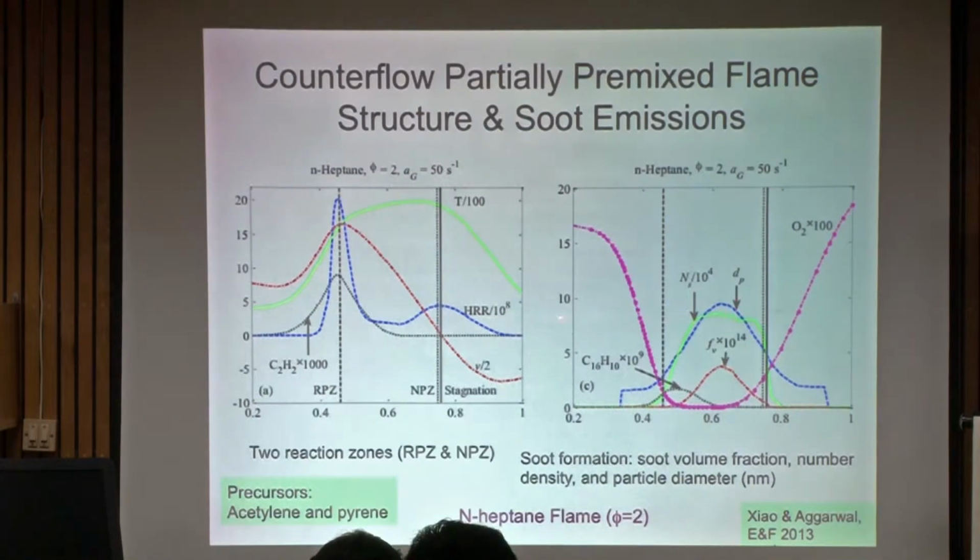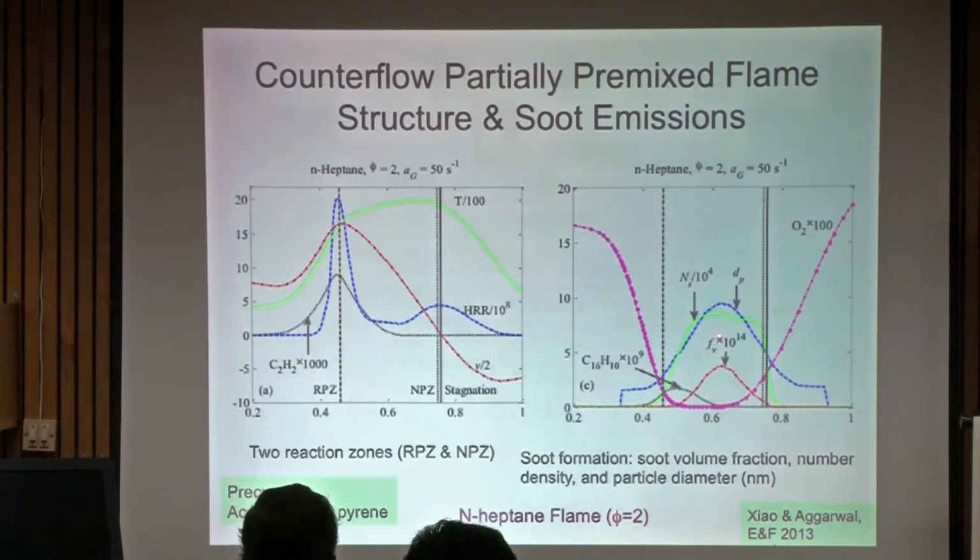So for particle size, the peak value is like 7-8 microns. Not microns, nanometers, sorry. Very small particles are found here. So you have three properties: number density, diameter, and we assume these are spherical particles in the model. And the soot volume fraction, which is this line. You saw the very typical behavior: soot volume fraction increases as the particles are formed, and then surface growth occurs.